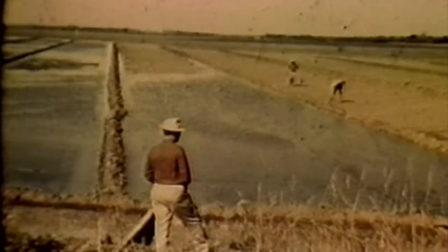Provisions for holding the water in the area to be irrigated are necessary to most surface systems. They're called levees, dikes, or borders. Each is essentially the same. They consist of a ridge of earth formed from the field soil to enclose the area to be irrigated. The term levee will be used in this presentation.